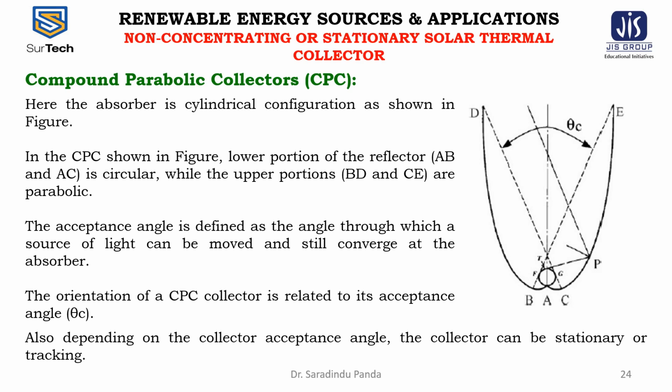The minimum acceptance angle in this case should be equal to the maximum incidence angle projected in a north-south vertical plane during the times when output is needed from the collector. For a stationary CPC mounted in this mode, the minimum acceptance angle is equal to 47 degrees. This angle covers the declination of the sun from the summer to winter solstice.